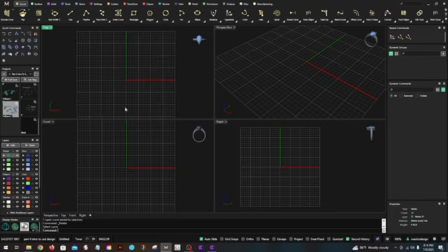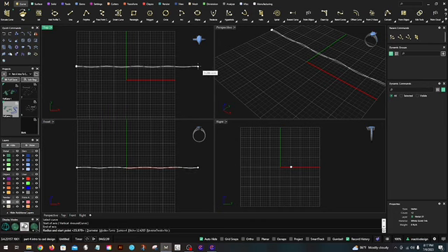I am going to change my layer color so that you can see it a little bit better, and it's in the lower left hand side, and I'm going to click on the little white square. Next we're going to do helix. Helix is interesting. I pressed on helix and I click and I click, and then I want to look at the command line.